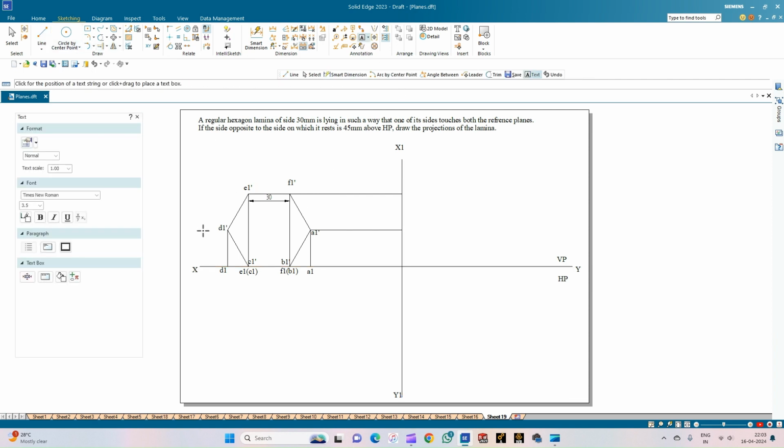So the side view, so the observer is looking from this direction. So for him here the corner E1 double dash is visible first. So let me call this E1 double dash, and inside the bracket F1 double dash, because the direction of observation is from the right hand side. So this is the view. So we'll be viewing the corner E1 and the F1 corner will not be visible.